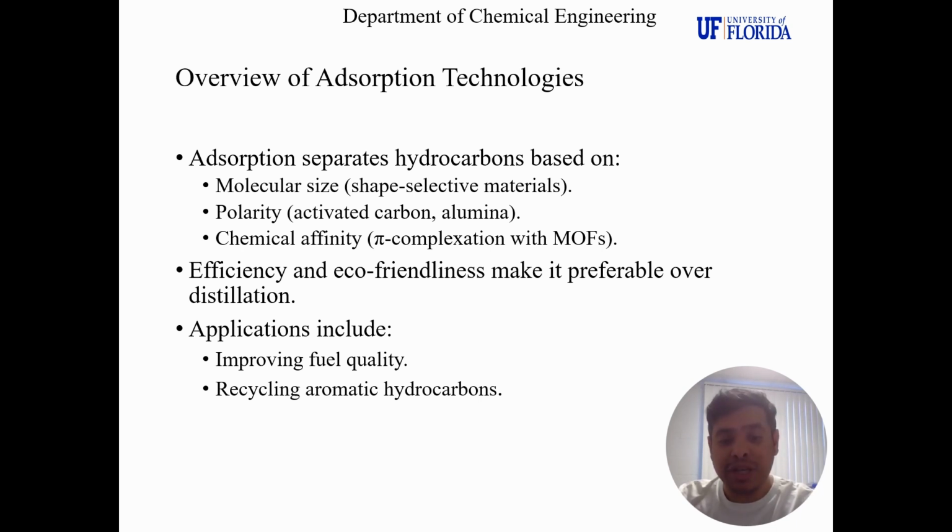Polarity-selective adsorbents, including activated carbon and alumina, separate compounds based on hydrophilicity or hydrophobicity. Materials enabling pi-complexation, such as copper-modified zeolites or MOFs, target aromatic and olefinic hydrocarbons. Compared to distillation, adsorption is energy efficient, cost effective, and environmentally friendly, with applications spanning fuel upgrading and pollutant remediation.